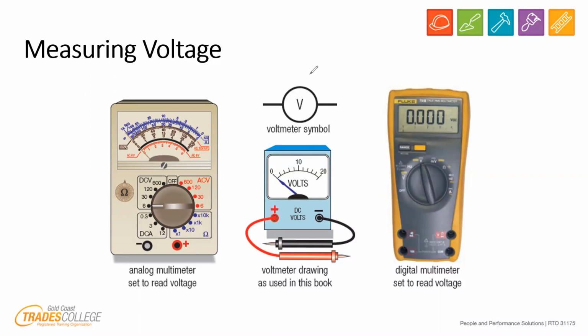All right, so measuring voltage is definitely the more common test you're going to be doing. Before you go to work on anything, you've got to make sure that it's dead. You've got to make sure that the supply is off. Measuring current, which we've covered in our first session, is something which, me personally, very, very rarely would you do on site. Maybe in my industrial work, I would measure it with a clamp meter, but definitely I can't think of an occasion on site where I'd ever measure current in series with a multimeter.